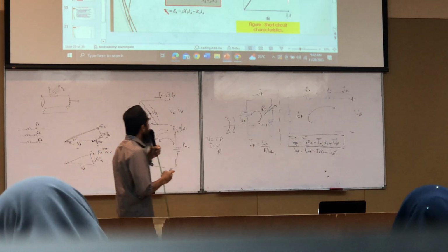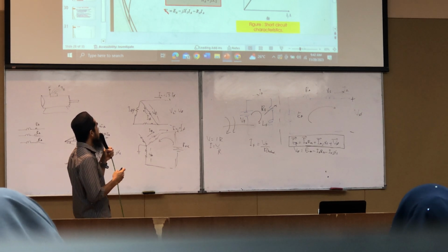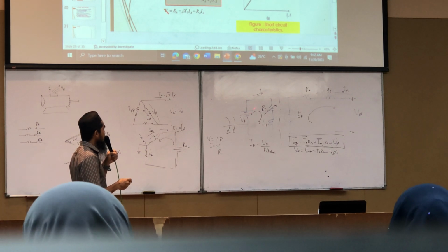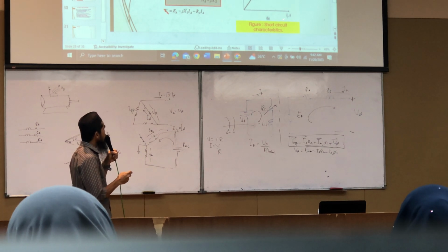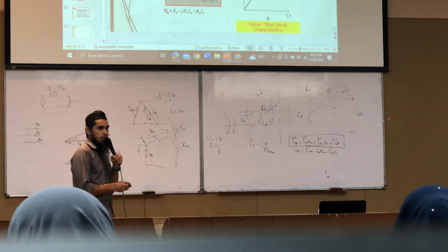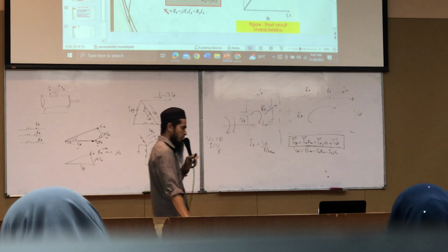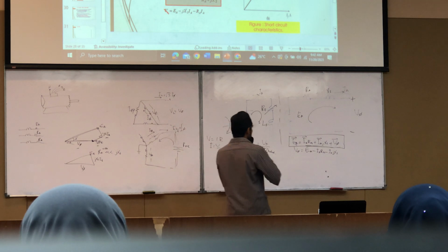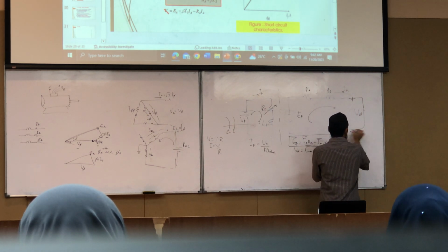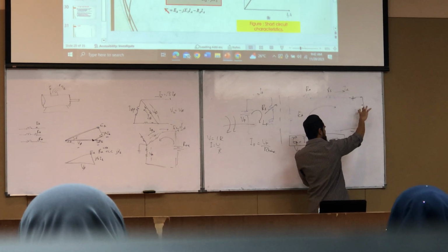Then you have to perform another test, which is the short circuit test. You repeat the same procedure, increase IF. Now you measure how much actually the current that flows. Is there any voltage when short circuit test? No. Why? Short circuit test means that you short the circuit, so voltage will drop to zero.